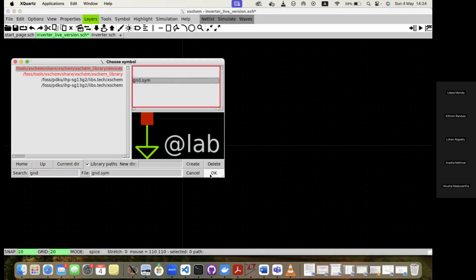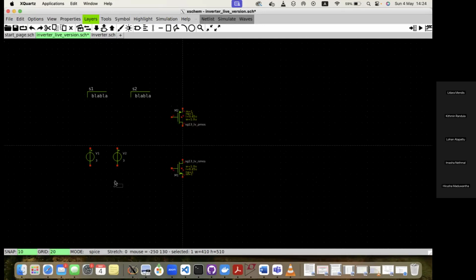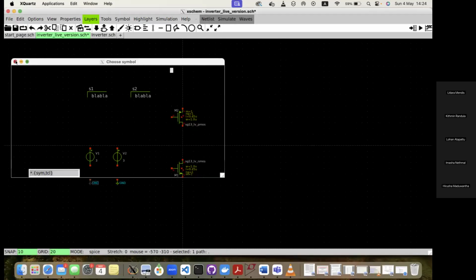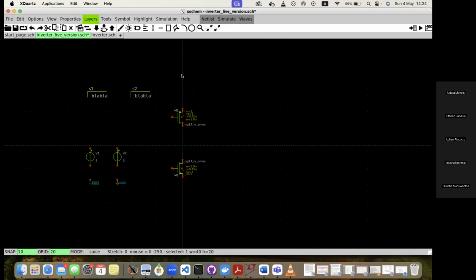Okay, there are several shortcut keys we can use. I will tell you about them. To open the components, we can use Shift I. For copying items, you simply use the C key, and then you can drag and drop and place it there. That's how it works.